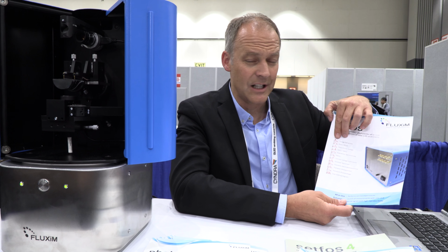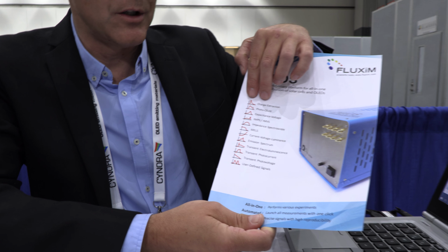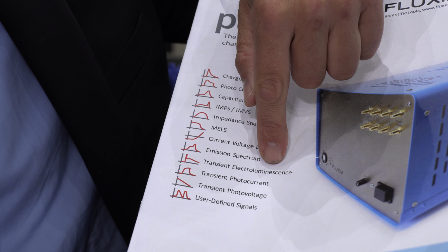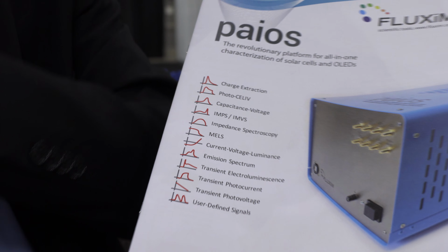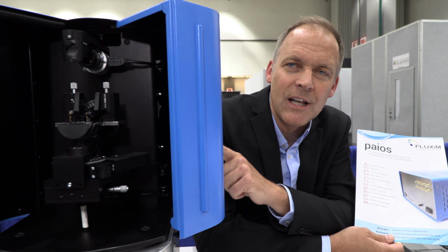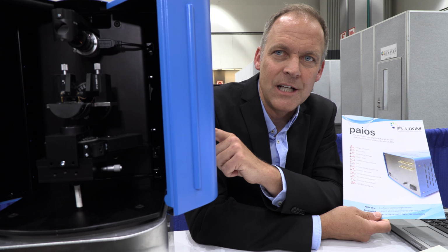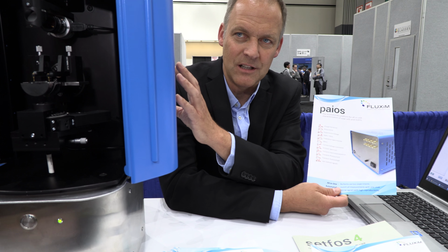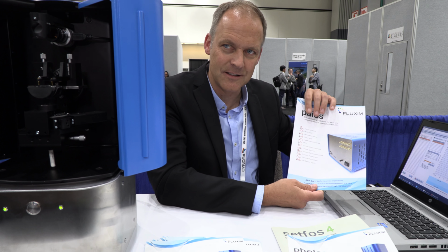What's the main difference between that and this? The main difference is this is focused on electrical properties of OLEDs, where we only look at, for instance, transient electroluminescence, which measures only the time-dependent light output. And here we have angular resolution of the light coming out. We get the spectrum of light and angular dependence, so it's complementary. This is more optical analysis, and this is more electrical analysis.